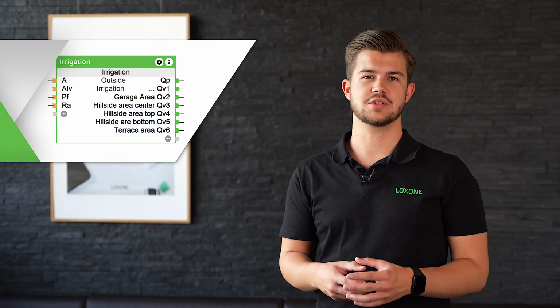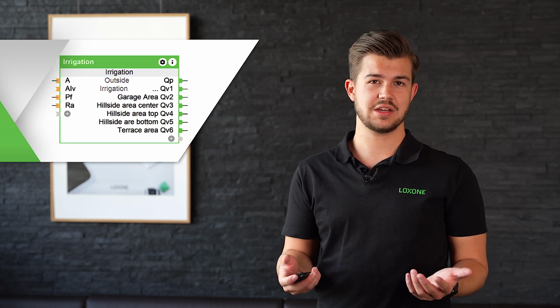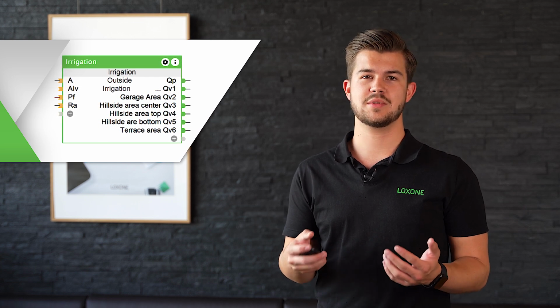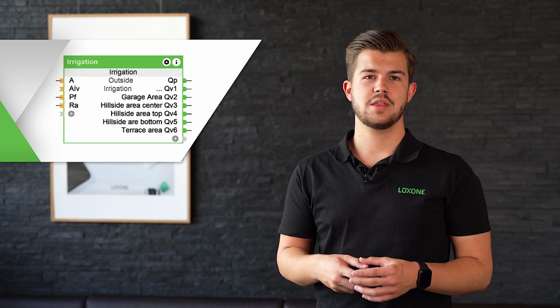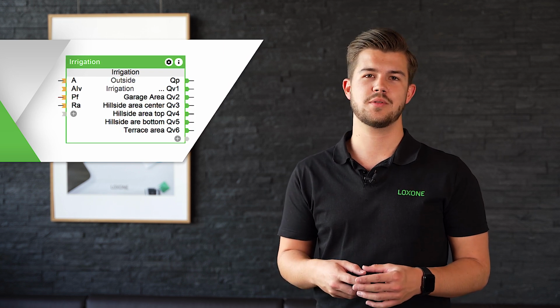A few weeks ago, with the release of Loxone Config version 12.1, we've added the new irrigation function block. This block enables you to incorporate weather data, such as precipitation and forecasts, into your home automation system, and thus enables demand-based irrigation. The function block has 8 outputs for controlling valves, as well as 1 output for the pump.